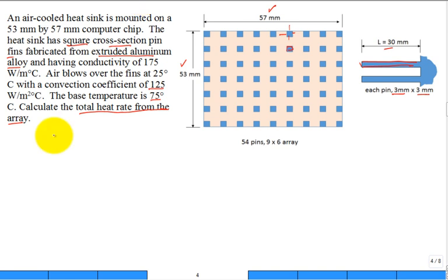Okay, so if I wanted to calculate Q, the basic equation would be get an h, get an A, multiply by the temperature difference, TB minus T infinity. But then somebody says, look, the base is at TB, but the whole pin fin coming out, down here it may be TB, and right there TB, but not out here.